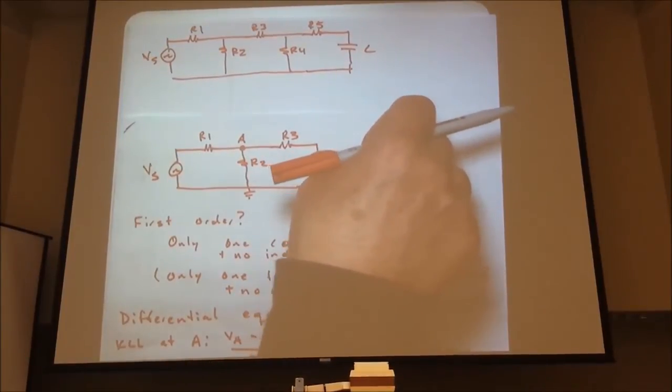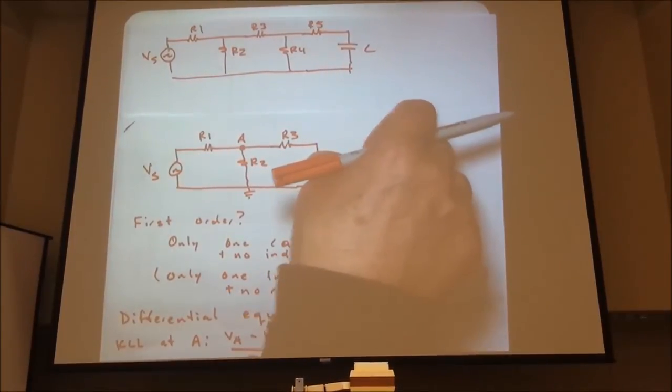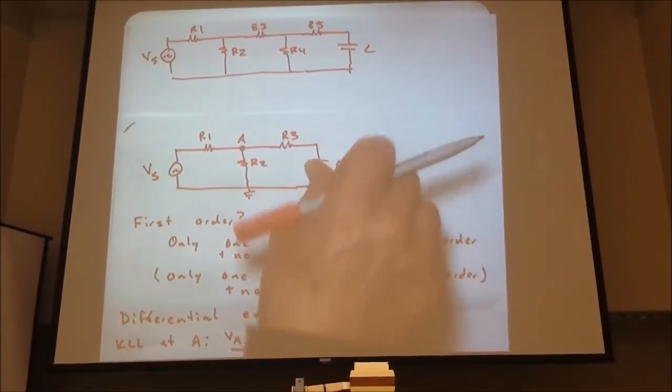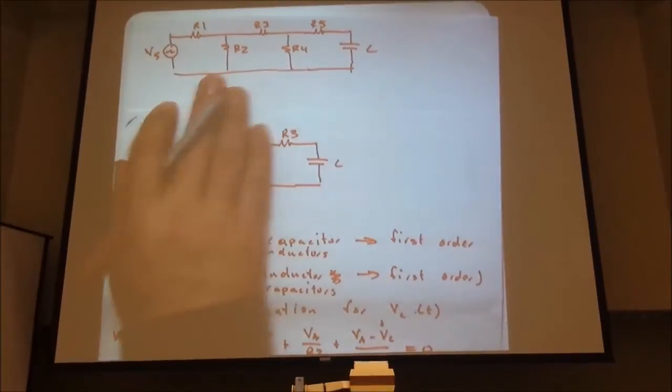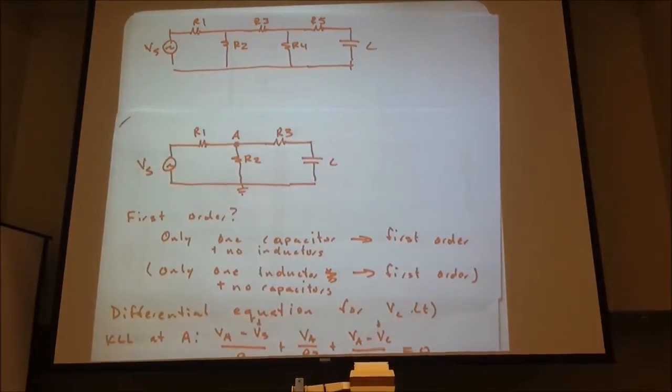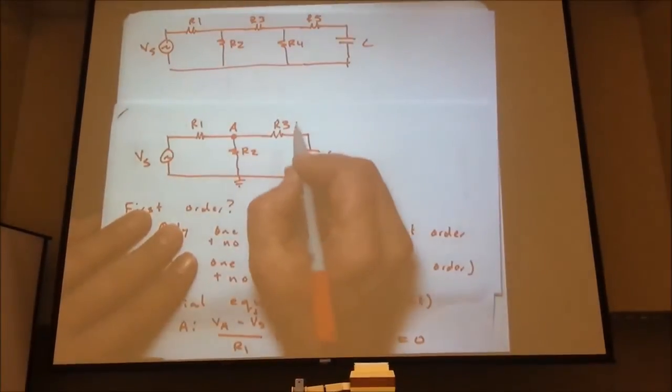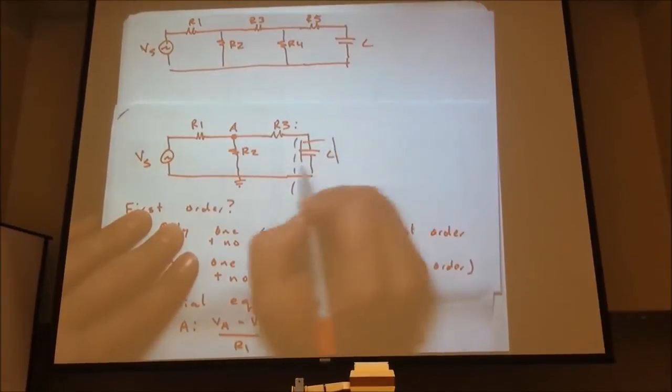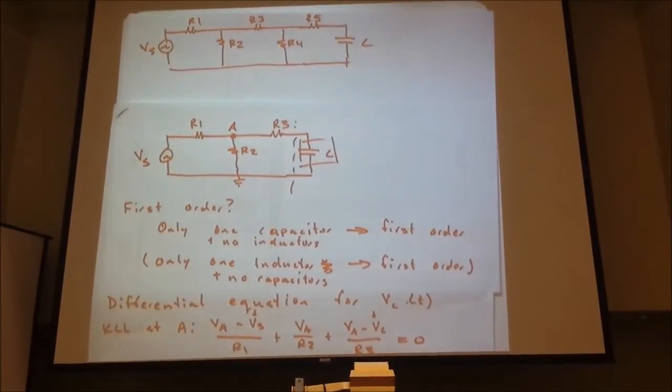You could do Thevenin and get a simple V Thevenin, R Thevenin, R load circuit, right? When we were talking about R load, I said it can be a whole mess of stuff. It doesn't matter what that load is. In this case, that load is a capacitor. And so this is just some arbitrary load. We can put a box around it. It is some black box load.